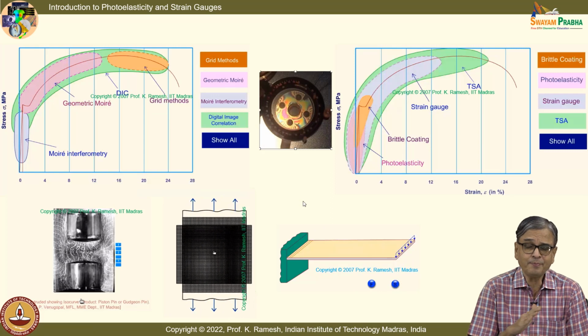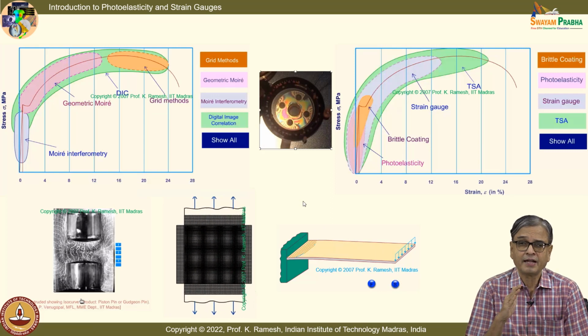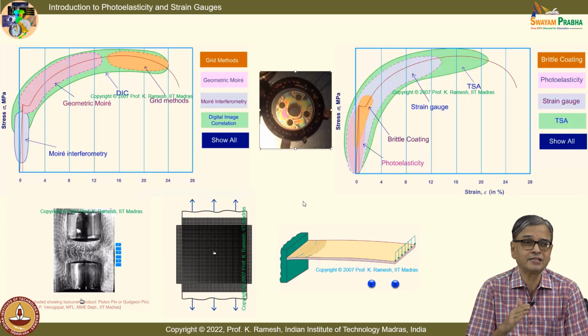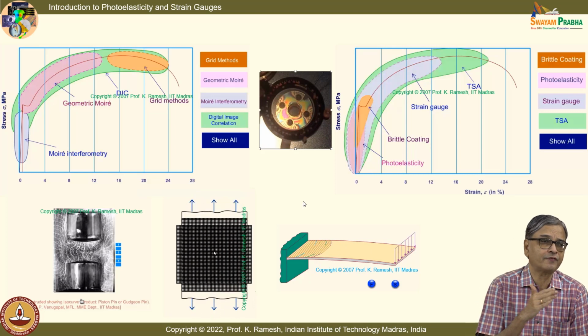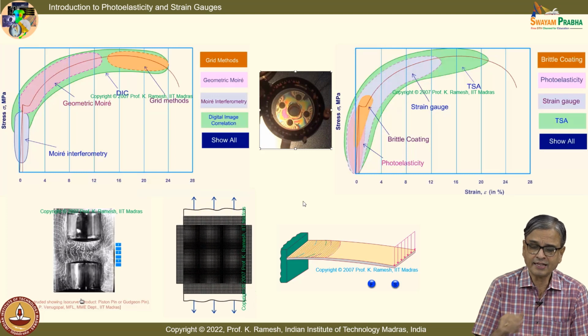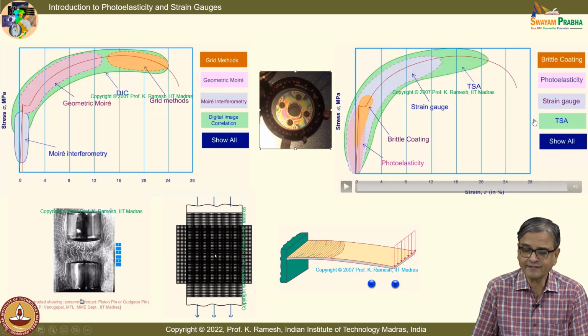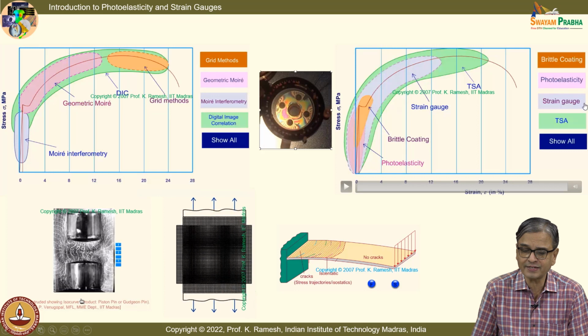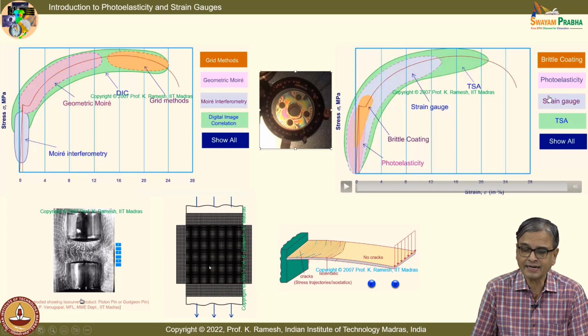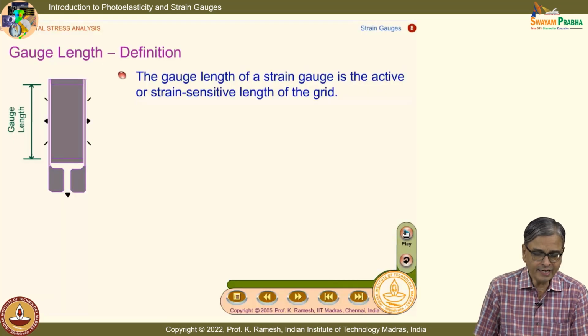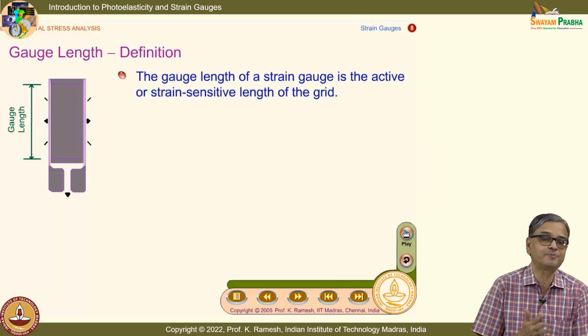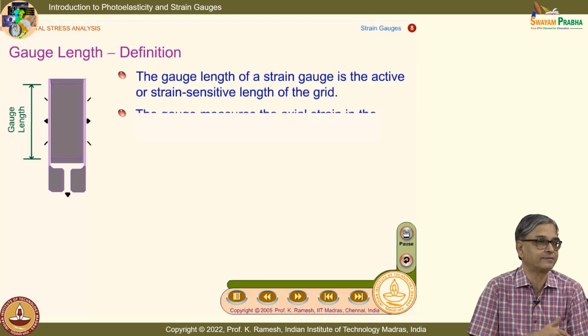You have multiple techniques. Many of them directly measure displacement. From the displacement, you find the derivatives and find out the strain. On the other hand, the strain gauge has an advantage that you have an electrical system that directly gives you the strain quantity. And many times, people say strain gauge gives me strain, which is a misnomer.